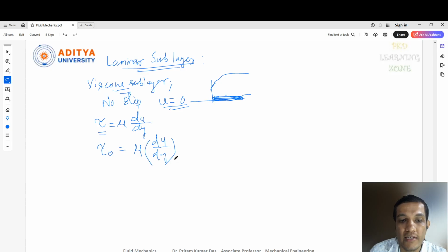Here y is the distance from the surface, and for linear variation we can write du by dy as u by y. So tau naught equals mu into u by y.